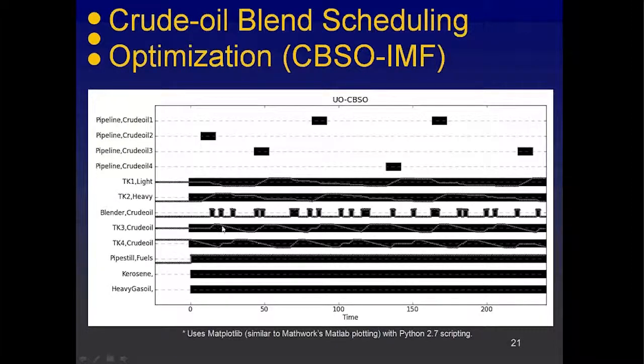There's also a run length for the flows of the crude oil that come from the charging tanks into the pipe still or crude unit, and that's why you see this. In this case, it was 19 hours. That's why you see a nice long flow out of a tank. It doesn't just flow in as fast as possible, but you see these nice stretches of flows out because you want to make sure that you can maximize the flow out of a tank going into the crude unit, because that can then define a nice crude run.